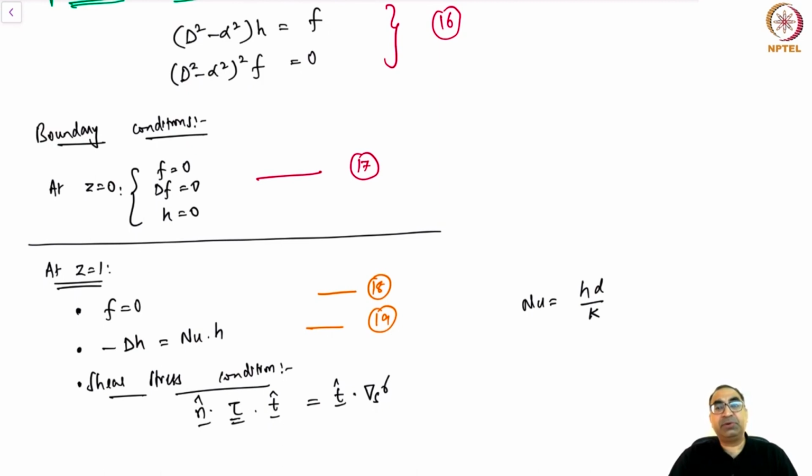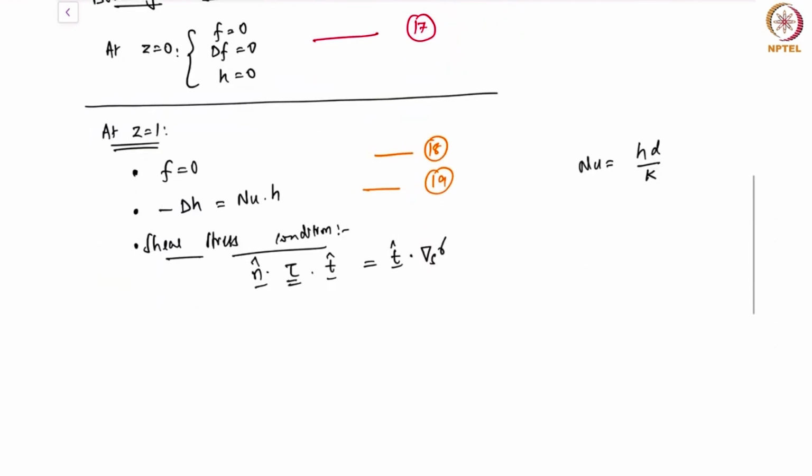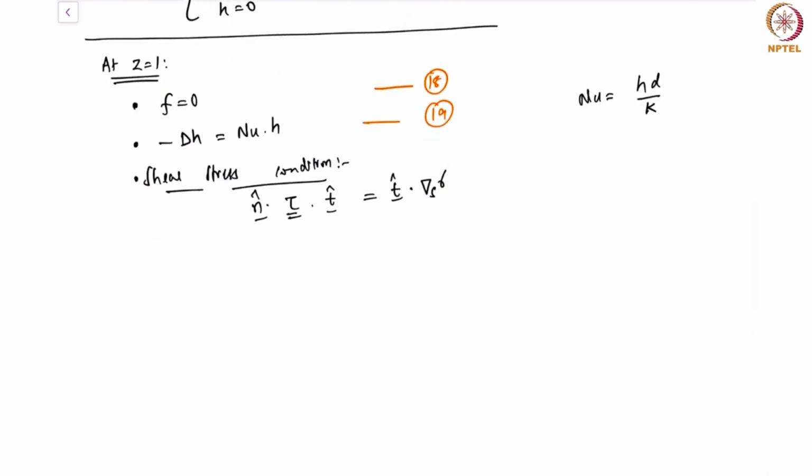We now have to derive one more condition at the interface, that's the tangential stress condition. And this is an important condition because this involves the Marangoni stress term. Note that this is a Marangoni driven instability, so this term is expected to become crucial for the analysis. So in the last lecture, we already wrote down the shear stress balance at the interface. Now the shear stress balance involves the surface gradient operator. The surface gradient operator, I will do it on the side here.